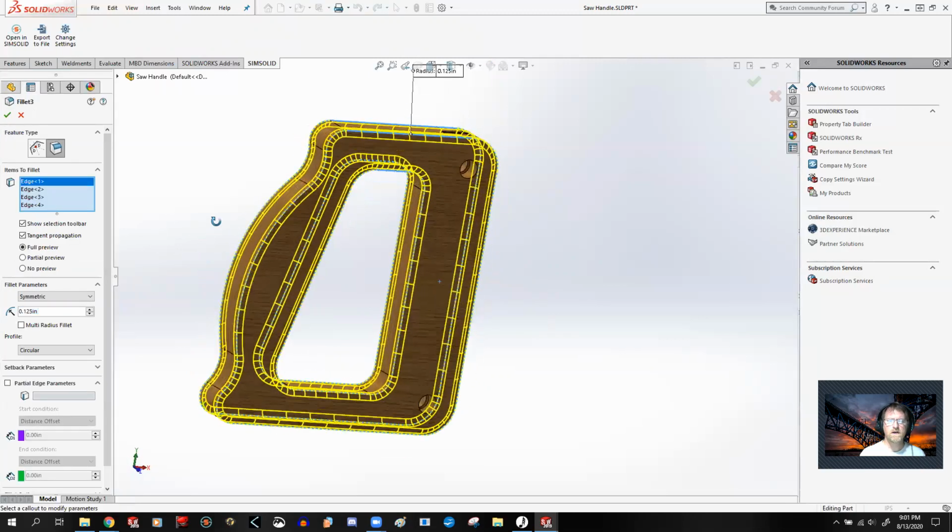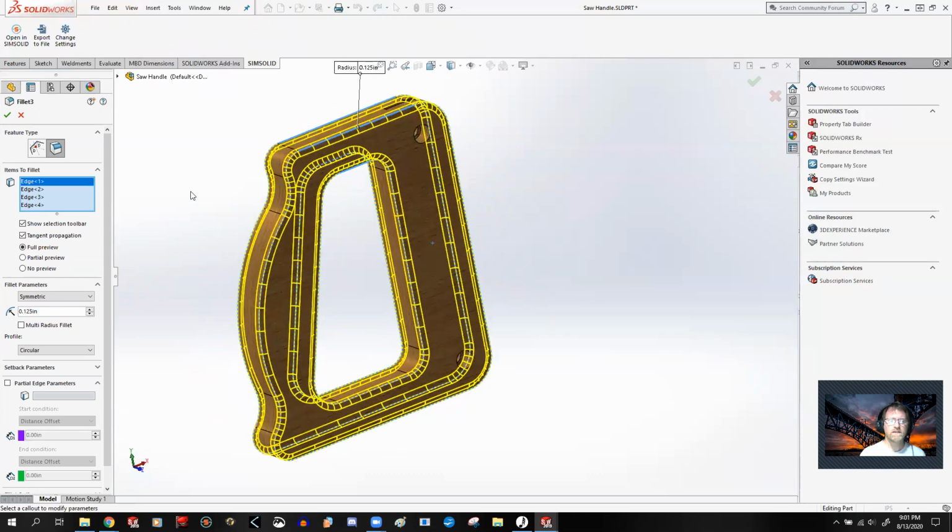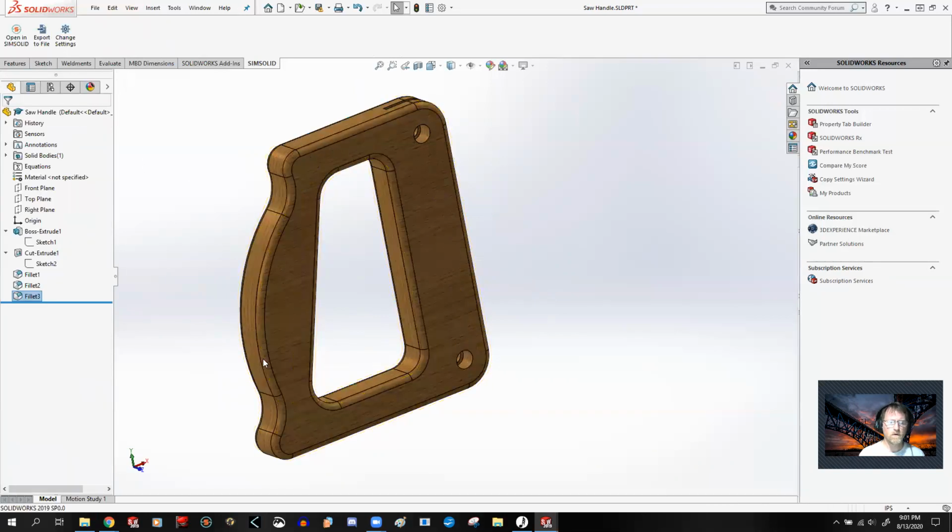Okay, yeah, these fillets are expected to be, they don't have to all be one fillet like I have here, one feature, but they do have to make sense. If you wanted to make 4 different ones, fine. Still makes you wonder why you want to have 4 different ones. But if you want to do the outside ones here in one, and then the inside ones, or the left and the right, that makes sense. But just kind of hodgepodging and having 18 different fillets. One of the key things is I've got tangent propagation that allows it to move smoothly all the way around and captures all of those. Yeah, that's all very well and good, but don't have them kind of hodgepodgey.